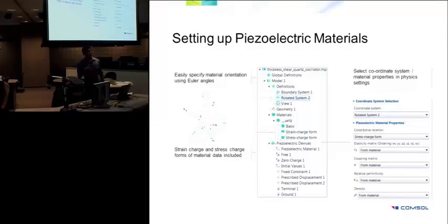In Comsol, all the default material polarization is with respect to the positive z direction. The properties are defined like that. If your material is polarized in a different direction, you need to define a local coordinate system that will rotate the default coordinate system in Comsol and calculate the equivalent properties in the rotated direction. I'll show you an example where this needs to be done.